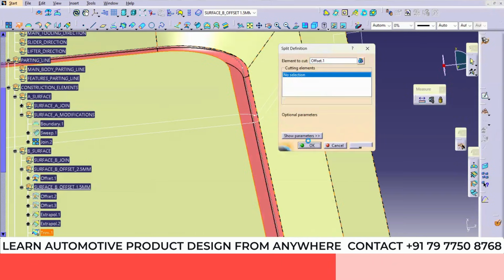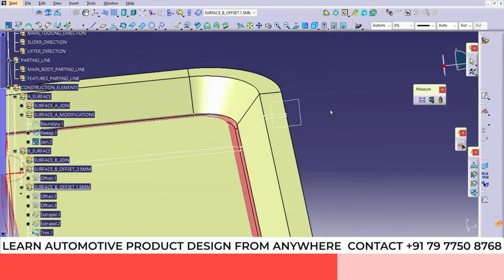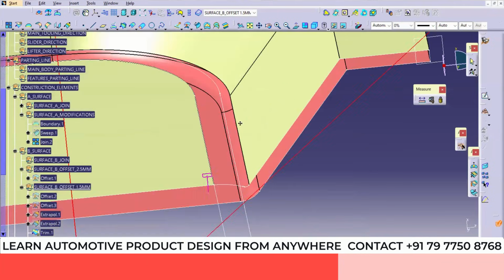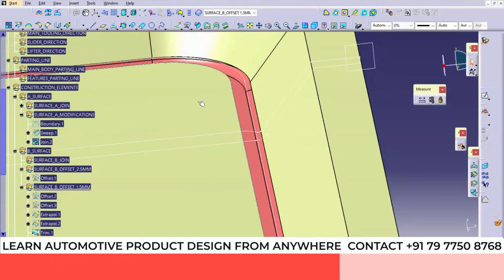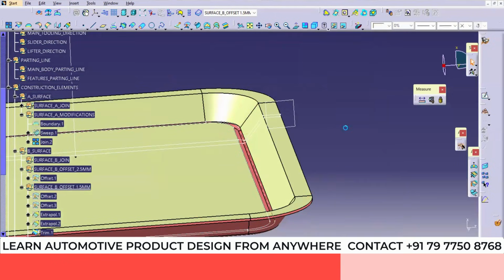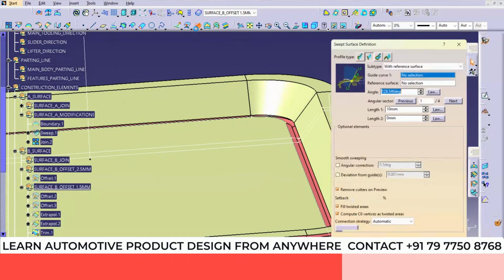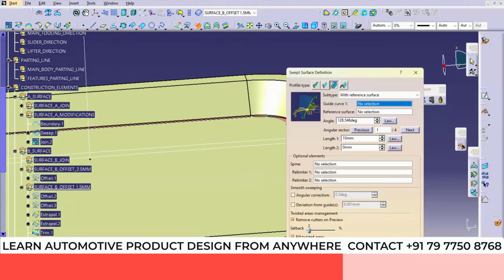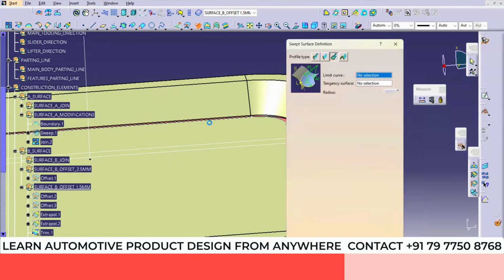Select this and use the split command. Okay, so now our condition is exactly matching till this, and now we are going to create a radius here. To create a radius, we are going to use the sweep command, then go to the circle type and select the limit curve and tangency surface.